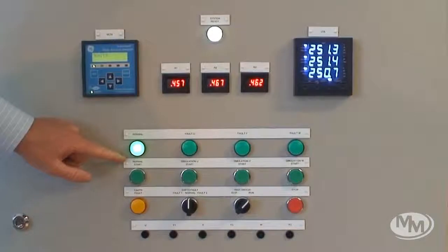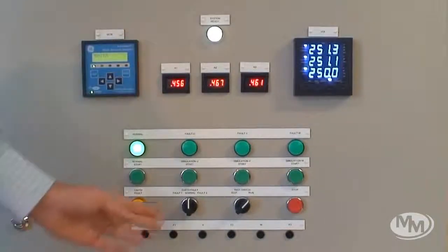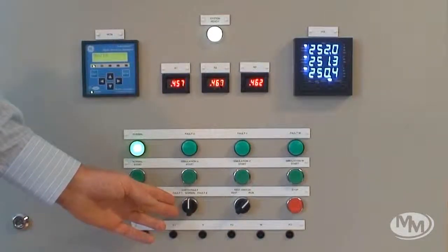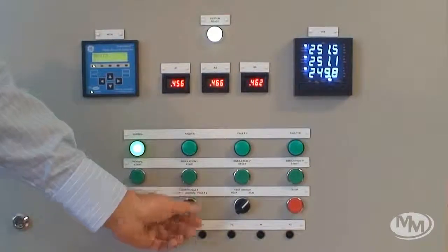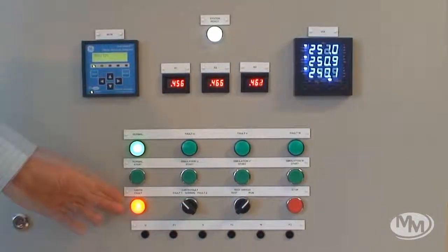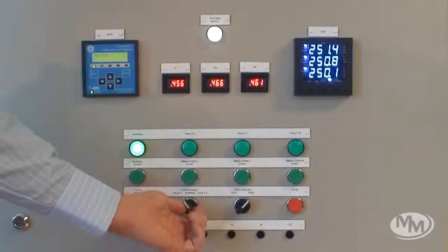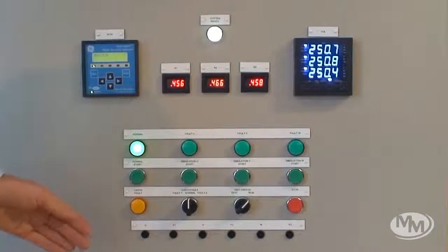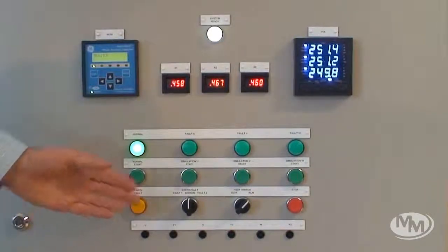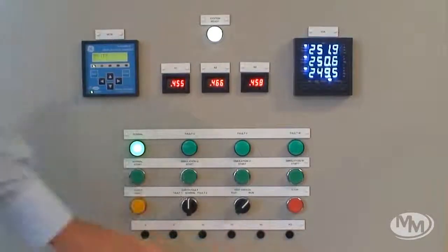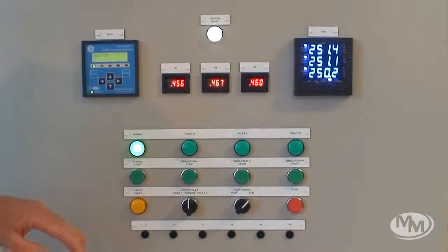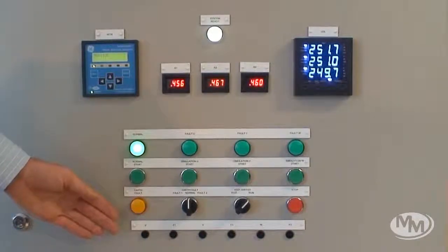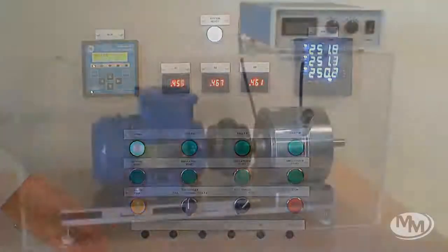We can also introduce earth faults. At the flick of a switch, an earth fault is introduced on the test motor's stator winding. There are two levels of earth fault, fault 1 and fault 2. These simulate a higher impedance fault and a lower impedance fault. The test points at the bottom of the cabinet are used for connecting external measurement equipment so that the faults and their nature can be independently monitored with test instruments and the outputs from the AnomAlert verified.